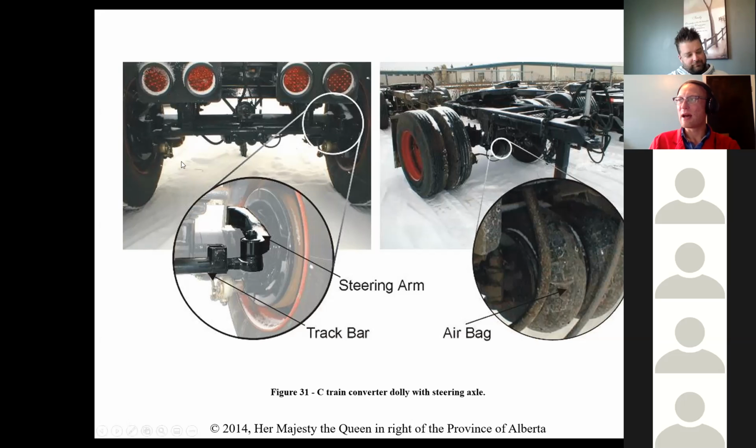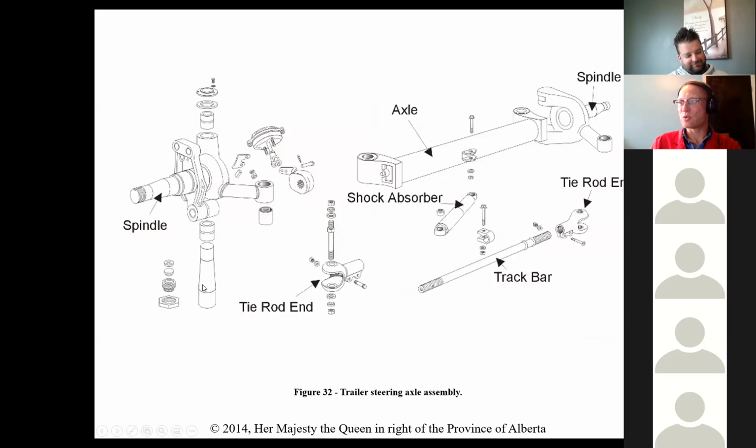And the kingpins I'm talking about are steer axle kingpins, the kingpins right in the axle that allow the steering knuckle to rotate. Just like these ones here. So this would be the kingpin here, the spindle, and the kingpin would go through this bore here, and these are exactly what they would look like. This is the large kingpin, and this is what you'd have to change. A little bit different now, they're actually not tapered like this, the ones that we were changing, and so they could come out from the top or from the bottom.